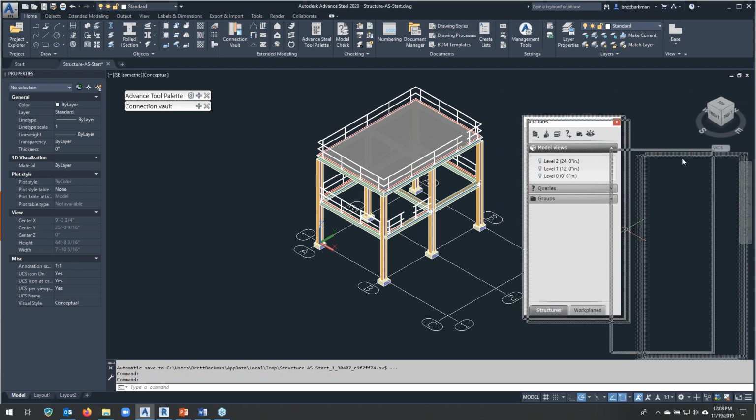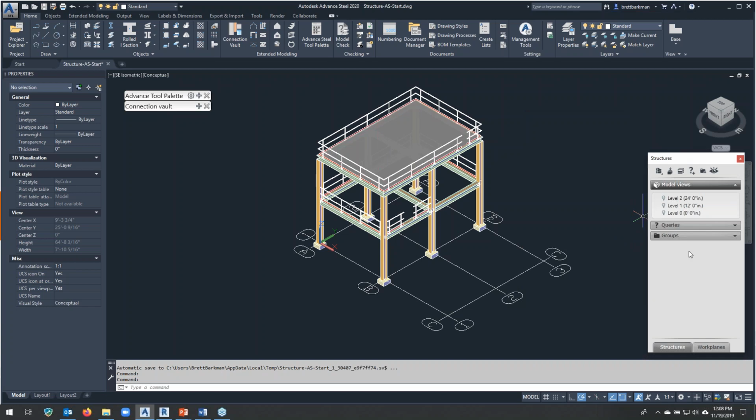With the Project Explorer, we will also have the ability to determine the lengths of things like our columns and provide constraints to the base and the top and tie those to our levels as well. And with this tool, it really starts to have a feel kind of like some of the features in Revit. So if some of you are also using Revit, you will see some similarities here. The difference is what the dialogues look like, you know, in the AutoCAD interface versus the Revit interface, but the underlying purpose is the same.